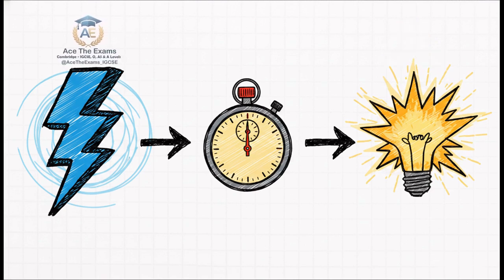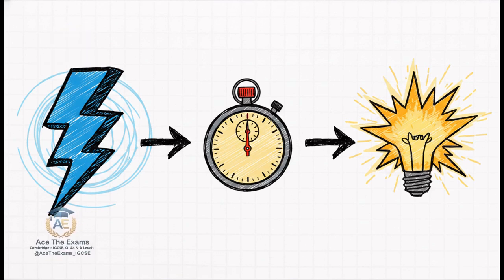To find the energy of a heater running at 5 amps and 20 volts for 3 minutes, I calculated 5 times 20 times 3, which equals 300 joules. Did you spot the fatal flaw? Sam forgot the golden rule.